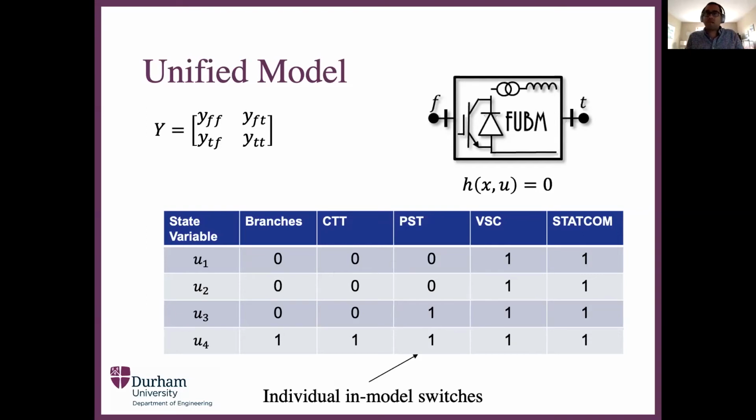So one of the challenges in modeling or solving power flows or optimal power flows in AC/DC systems is that you have distinct grids. You have a DC grid and you have an AC grid, and they are isolated from each other by the converter. So you need to solve the DC grid first, then plug in those results, do a representation of the DC grid in the AC grid, and then solve the AC grid.